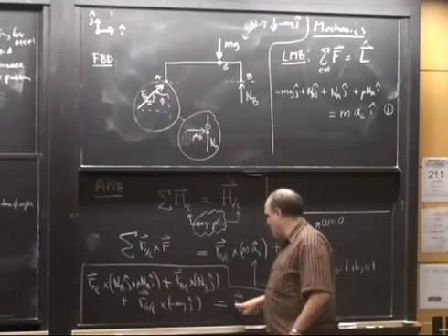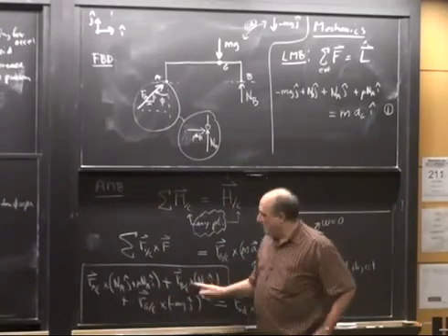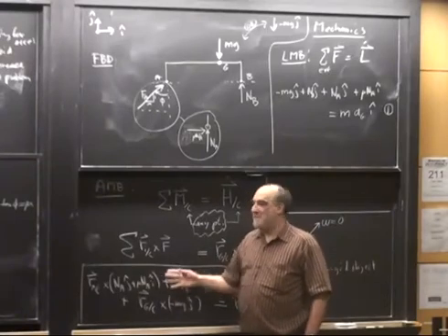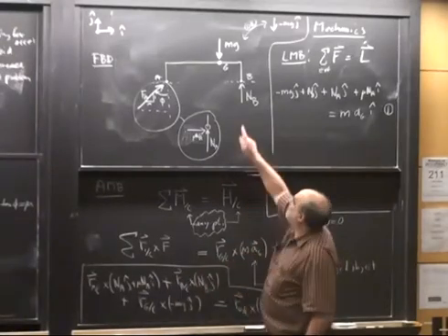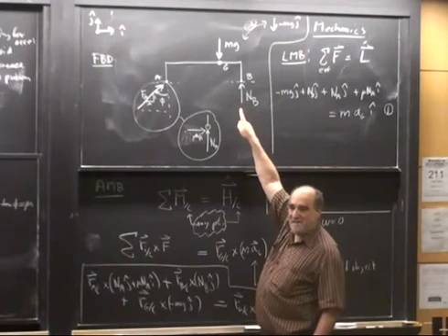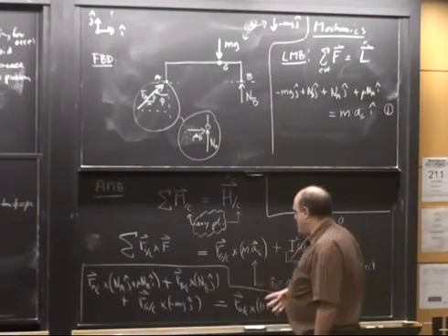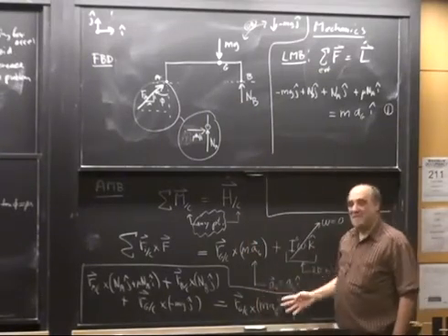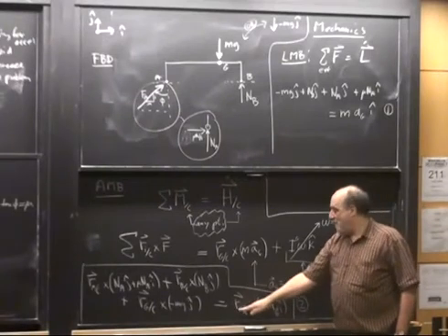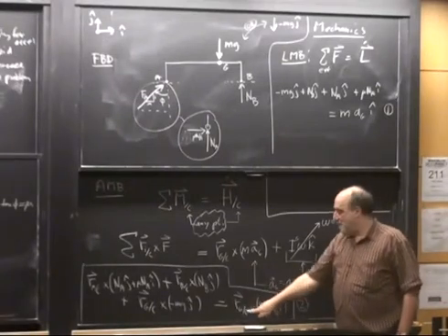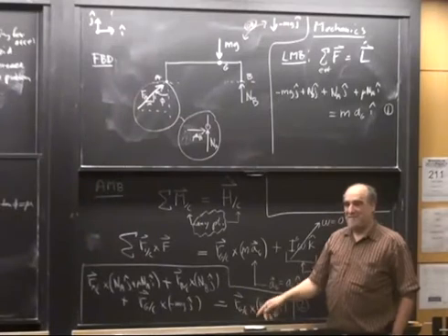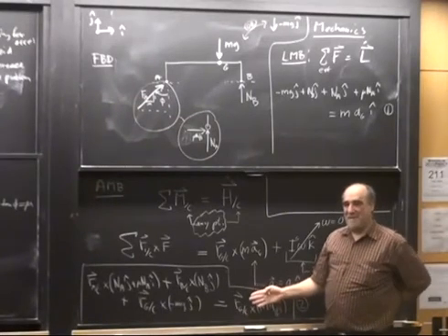You're talking about this term and this term? Yeah. Okay. We have to look at the sum of the moments, and that has to do with the forces, and there's a force at point G. And that's equal to the rate of change of angular momentum, which has to do with the acceleration of mass, and that's r cross ma, and that's also the position of G with respect to C. It's 2 different things, the left side of the equation and the right side of the equation.